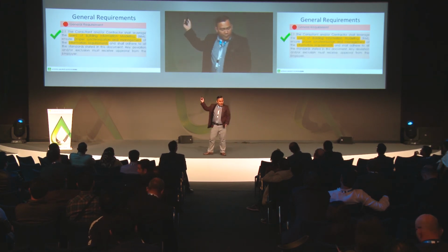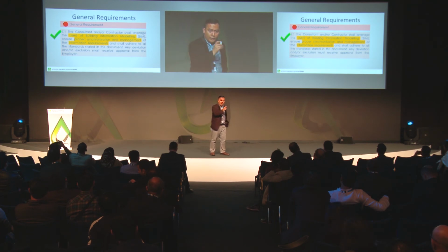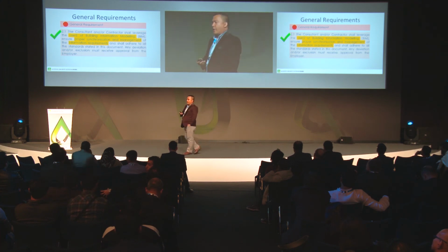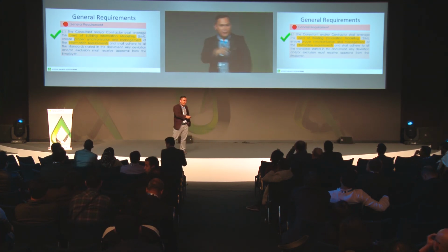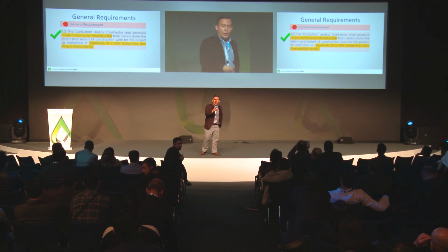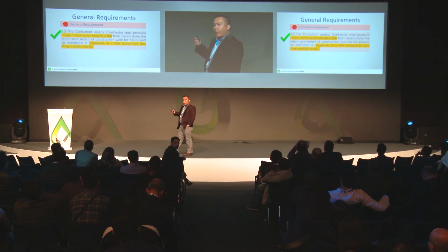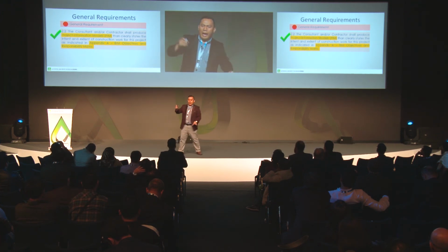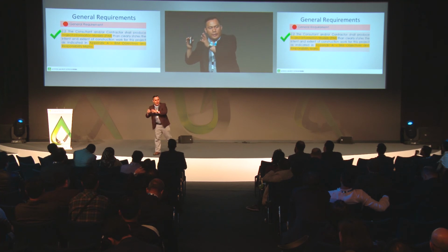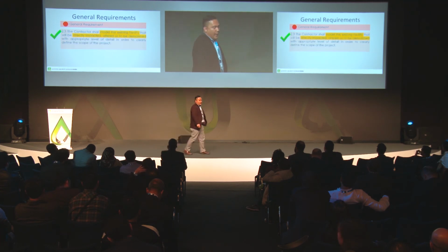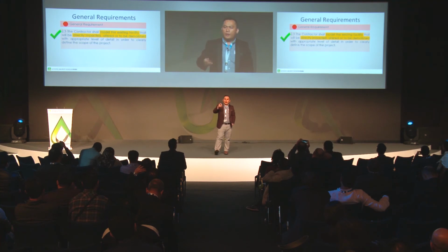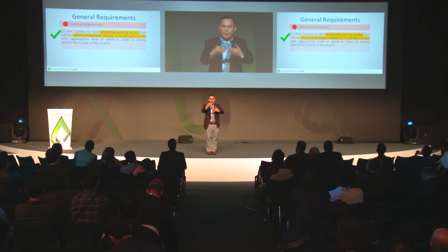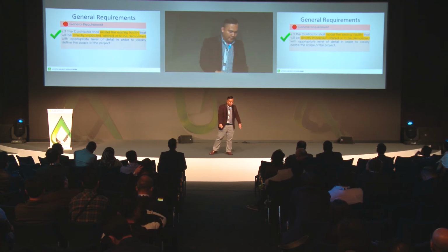So this is the example sample clauses that should be integrated to the contract or the BIM specification. Let's say the use of building information modeling and proper synchronization management of information requirements. And then we have also the creation of project information model or asset information model. So project information model is actually a design model and construction model. Asset information model is basically what we call the as-built model. And then we also mentioned that if this is for an existing facility, you have to model those existing facility and the interfaces of those existing facility to the new facility.